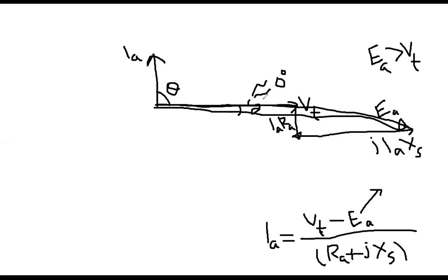There can be 1 or 2 degrees in real practice, because I am drawing by hand, but at least you can understand that it will not be much. In the cases that I discussed a few minutes back, your delta will be very close to 0. That is the meaning of no mechanical load. So under this situation, that motor will start working as a capacitor, because I started this way, with theta fully 90 degrees.